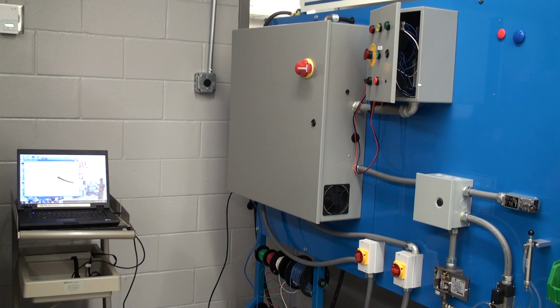When feeding wires by hand, it is common practice to tape the ends of the wires together. This makes it easier to push them through the conduit. If the wires snag while feeding them through the conduit, wiggle the wires or pull the wires back to free them and then feed them forward again. Continue to hand feed the wires until they appear in the panel to which the wires are being fed.